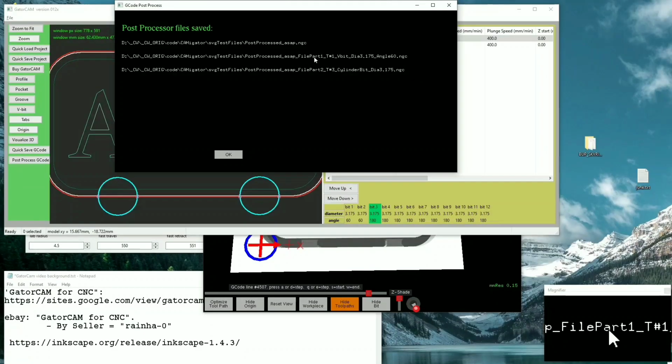It'll try to do all the same tool bit first, and then it'll go to the next tool bit, so you don't have to change your tool bit more than twice. But if there's a cutout, it intelligently knows we're going to be cutting something out, so we need to do everything before we cut out. In that case, it'll rearrange the order of the G-code so that you don't have to change the tool bit as often as other programs might require.